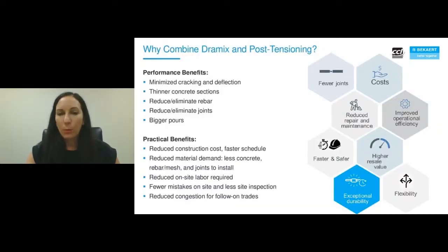Now, why would we do this, right? These are 2 great systems on their own, and so we're really maximizing all of the benefits of both, right? You get minimized cracking and deflection, thinner sections, reducing or in some cases eliminating rebar, as well as joints, and having really huge pours. On the practical side, we have reduced construction costs, faster schedule, reduced material cost, right?